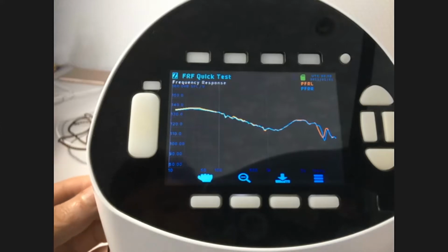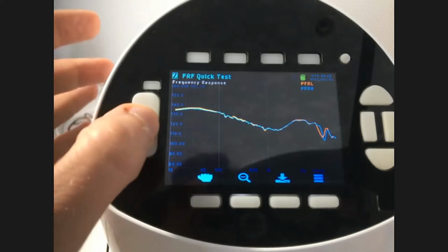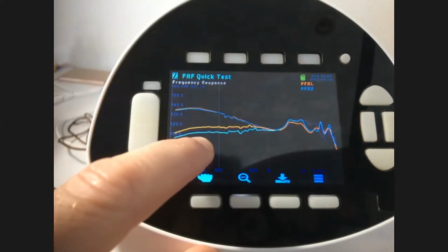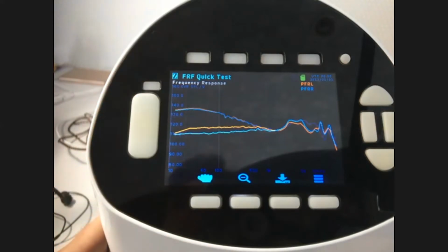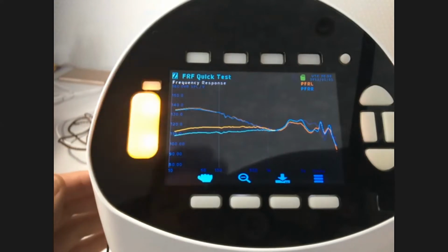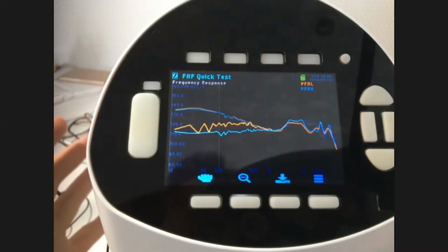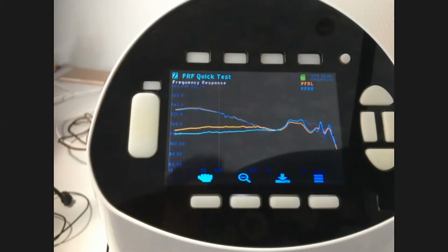It's quite obvious looking at the curve. They've played around with that tuning to get it to be as flat as possible, and they've done it pretty well. Basically, they've got this set up nicely. We do notice that the left and the right have different levels, so there's a bit of a channel imbalance there, which is not the best. That might be just due to the variation in the leakage, from one piece of filter paper to the next. Especially if you're using the cotton paper type of thing, there can be quite a bit of variation. So it's hard to control.